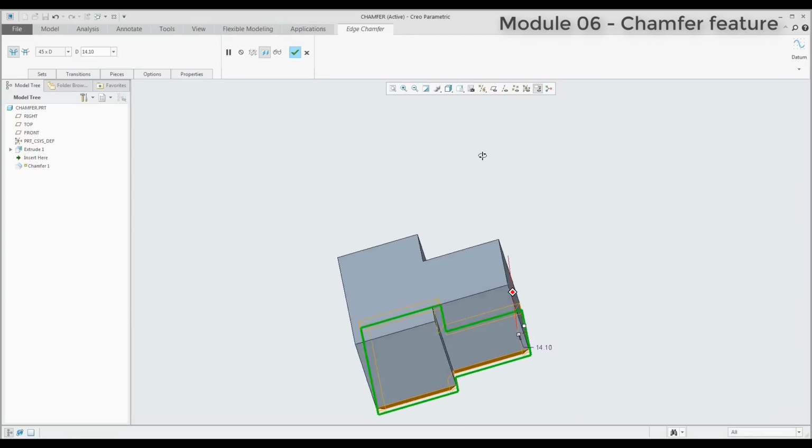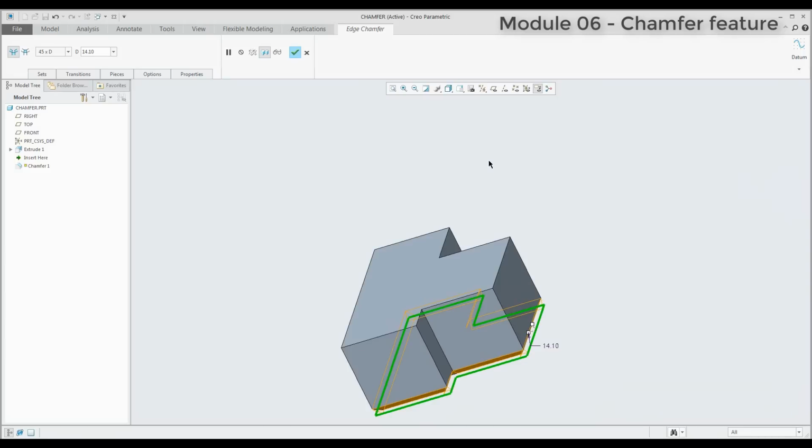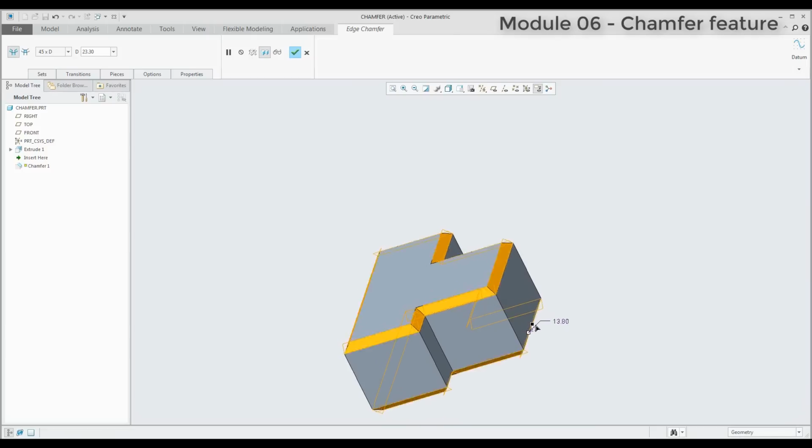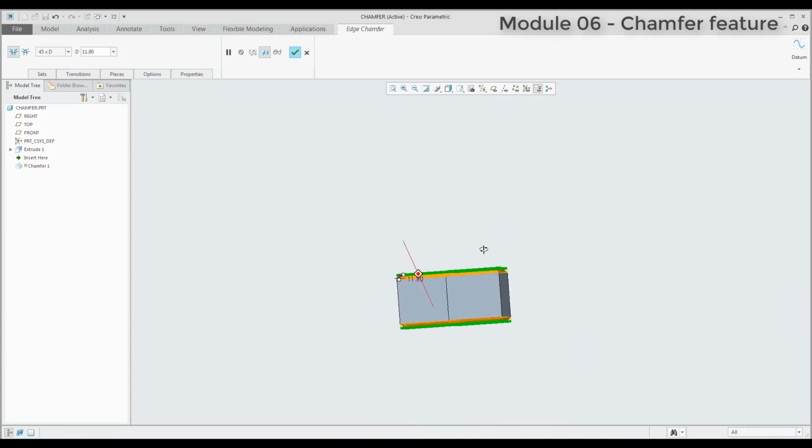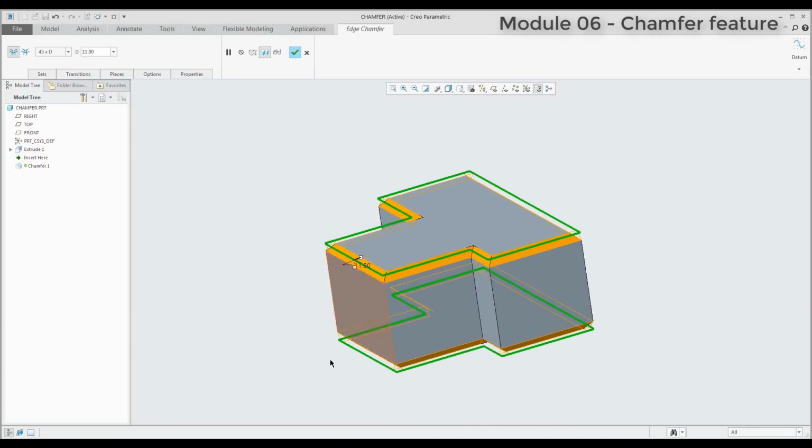You can use it on the bottom too. So for example, if I use the control button and then right mouse button and left, the system will create the same chamfer on these edges. And you would like to ask me if it is possible to create vertical intent chains too. So select again the control button that I'd like to add, and right and left.